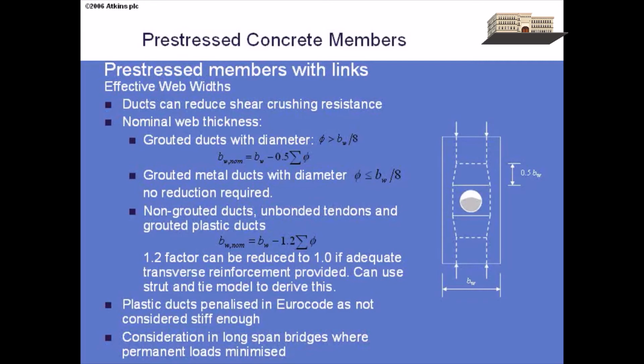Now this is a bit unfortunate because one thing we're trying to do in industry is move people across to using plastic ducts because they're better for durability than steel ducts, and this punishes you for doing that. So in one of the committees that I'm involved with, we're trying to do a bit more testing on this to see if there's some justification to go back to using the same rules for steel and plastic. Some of the tests show it makes no difference, and some show that plastic is quite a lot worse, so it just depends on which set of tests you take at the moment.